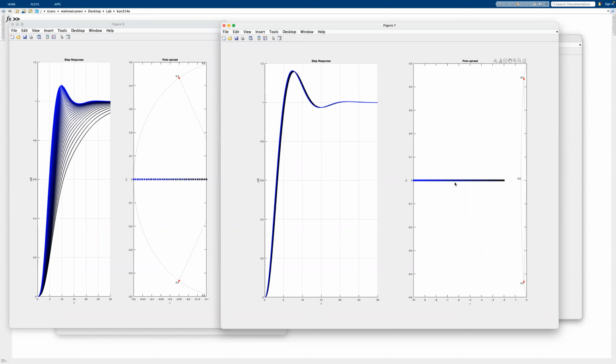But here the pole has slight effects on the system's behavior. So when we calculate all the settling times, overshoots, rise times, since the shape of the system does not vary that much, I don't say that it doesn't vary at all, but it doesn't vary that much. So that's the keyword here. So we can assume that we are okay with that.